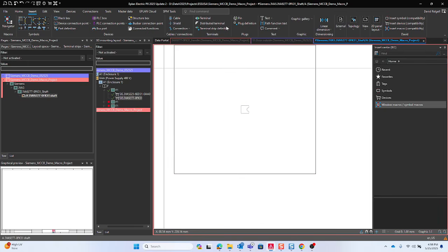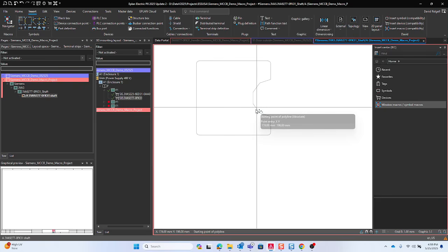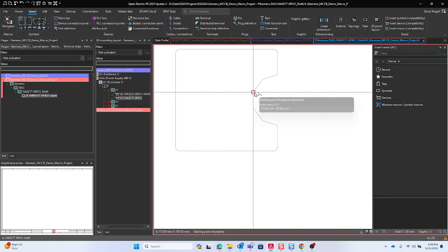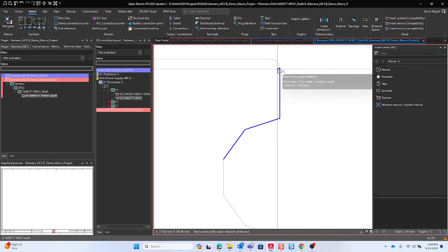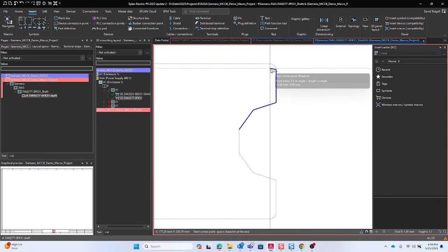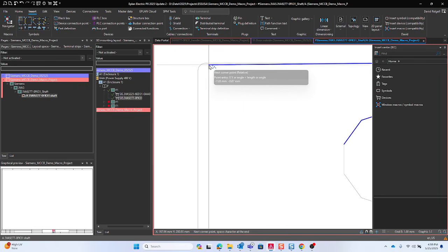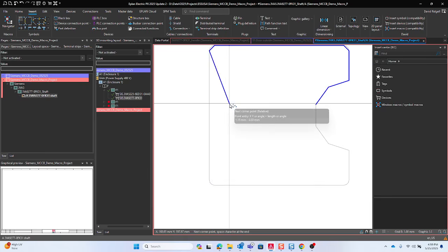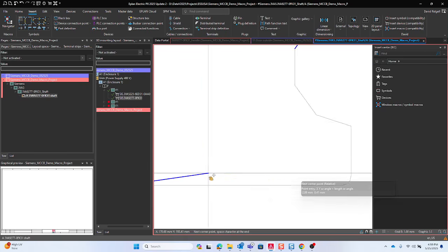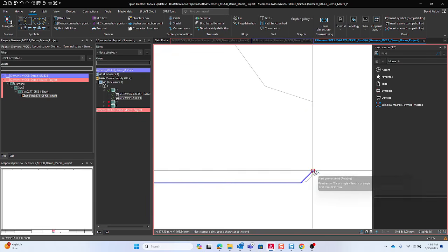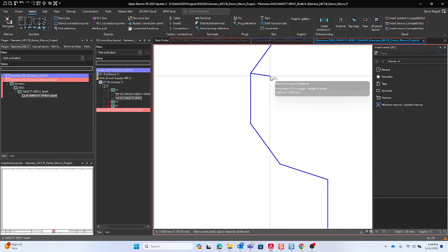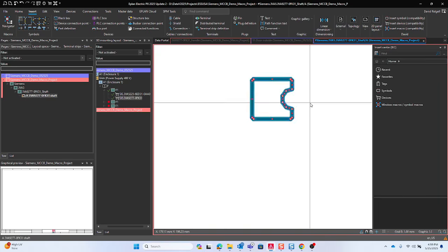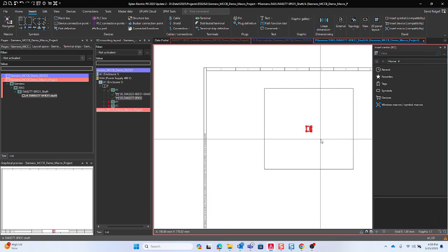So what I can do is we'll draw a polyline. We'll draw a polyline around this. I'm going to turn O-snap on and turn grid off. Doesn't have to be too precise. Just kind of skip some of those like that. This will be good enough, frankly. It's not something where we have to get overly precise. When we get to the end, we'll just hit space to complete it. Okay, so there is our polyline.